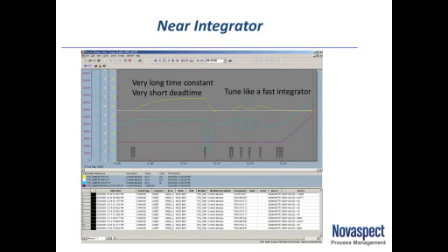So what we can do is we can tune this with the integrating rules, the rules we would normally use for a tank level, and use that guideline I gave you here of choose a fast lambda time, 3 times your dead time. Now what that does for me, I don't have to wait for this 10-minute change. I can make a change in just a few seconds. I can see my slope. I can make a change down in just a few more seconds.